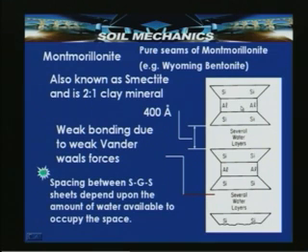one alumina sheet and two silicate sheets form the elementary layer in the case of montmorillonite, and these elementary layers are separated by several water layers and cations, because of the weak van der Waals forces. Because of the weak van der Waals forces between these two elementary layers, the spacing between the silicate sheets depends upon the amount of water available to occupy the space. The more water, the more the spacing.